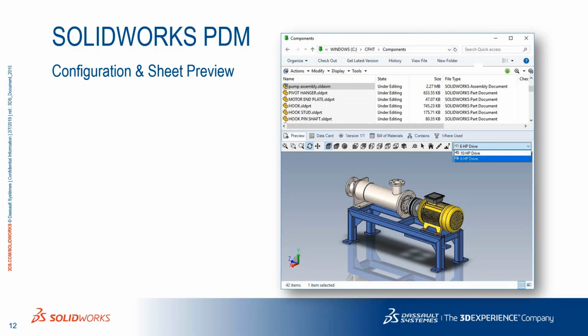Also, a big improvement, we're going to see this in eDrawings as well, is that the eDrawings preview built into the PDM Windows Explorer Vault view now supports configurations, so you can actually jump between different configurations of a SolidWorks file in the preview window without having to open SolidWorks or open eDrawings, as well as sheets in drawings, to be able to move between the different sheets and not only see just that one active sheet like we've had in the past with the preview pane.